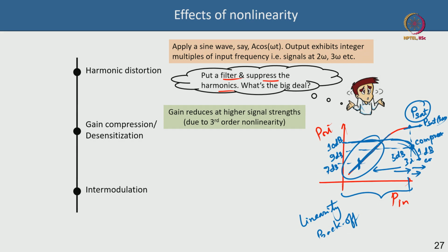Okay, so it is called 5 dB back off, 3 dB back off, etc. You want to operate at back off because you want to exploit the linearity. The disadvantage is that although your gain is very high, your input power is very low, and so your output power is also going to be very low, correct. So you always have to have these trade offs anyways.